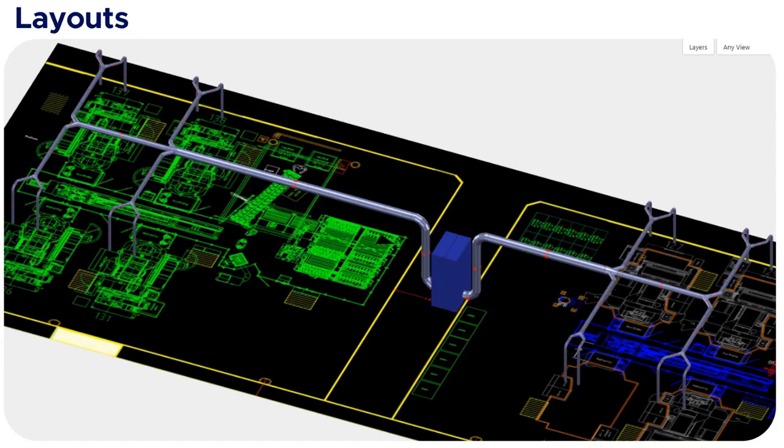It works extremely well. This is usually a little bit more CFM than we actually needed, but these machines had some pretty big cracks in them as far as spaces where mist was getting out. So I had to add a little bit more CFM to make sure we had negative pressure on that cell or machining center to keep the smoke inside when they open the door up. And that's how we determine how much CFM we're going to need.